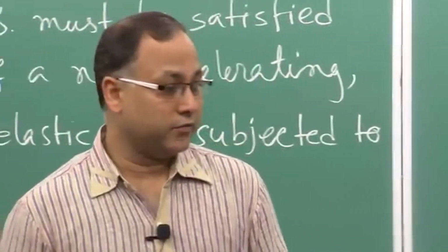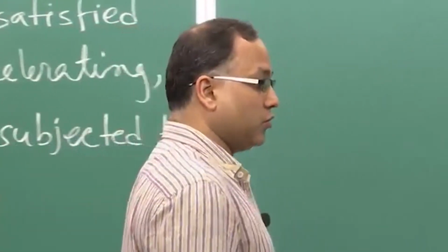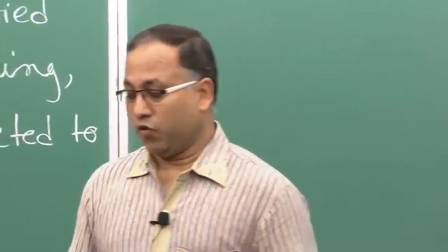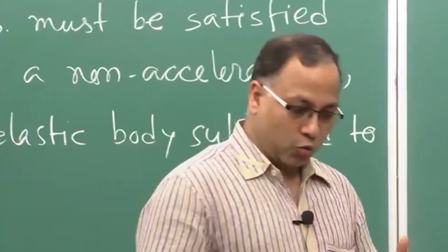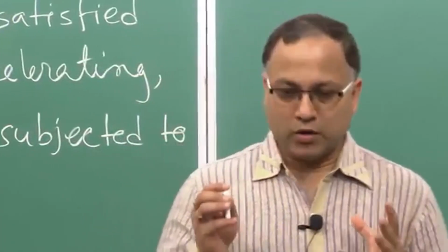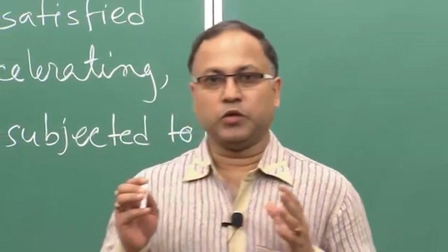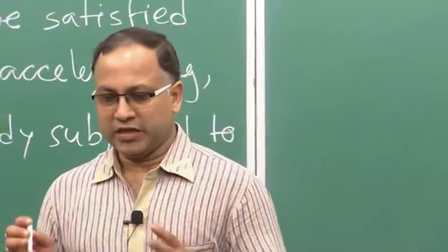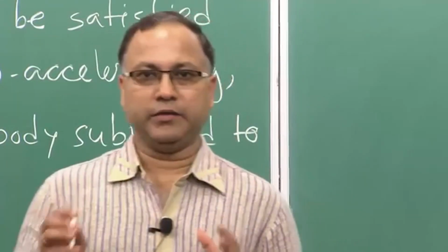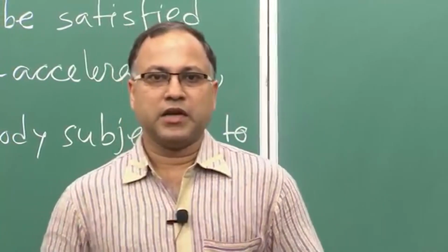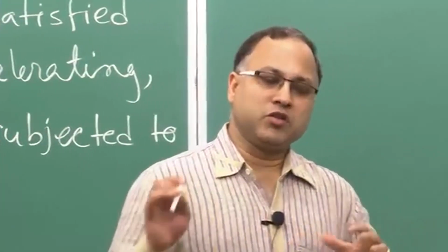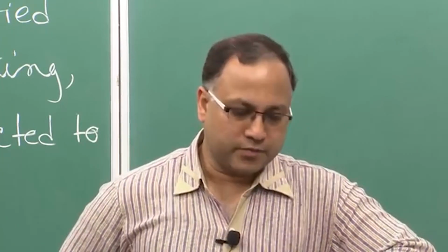Welcome back to the course Mechanics of Solids. In the last lecture, if you recall, we talked about the stress strain relation for the isotropic material, and there we concluded that the normal stress only develops normal strains and shear stresses only develop shear strain, right. Based on that we established the generalized Hooke's law, and the relation between the stress and strain, right.